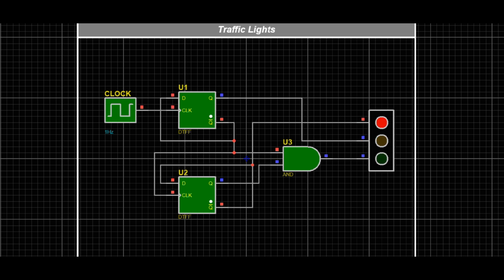It also has 2 outputs. Q, normal output, this holds the stored value. Q inverted, inverted output, this is the opposite of Q. In simple terms, when the clock signal changes from low to high, the D input value is transferred to Q and remains there until the next clock pulse.